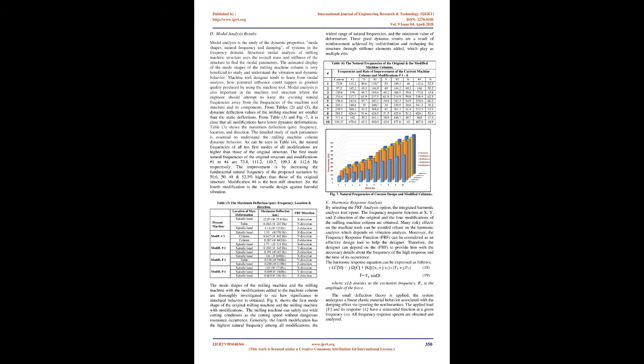Elasticity is recommended. Higher stiffness mitigates the milling machine's deformation. The results show that higher rigidity, higher natural frequencies, and lightweight machine tool structures are the best from static, dynamic and feasibility points of view. These goals have to be considered while designing the column of the milling machine. Stiffness is the degree to which the structure resists deformation as a response to an applied force. The stiffness is defined as the ratio between the applied force and deflection. The stiffness of a structure is of major significance in machine tool structures, so Young's modulus is the most important property considered when selecting a material.